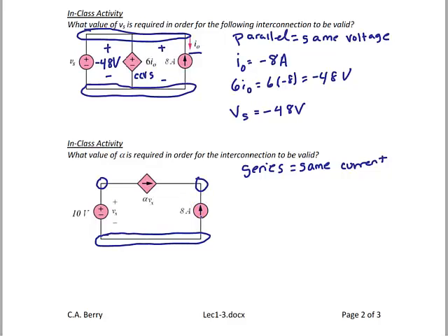So what that means is that if I have a current source of 8 amps that goes up, then I also have 8 amps that goes to the left, 8 amps that comes around counterclockwise and goes down into the 10 volts, and then the 8 amps returns at the bottom back to the source. So I have a voltage controlled current source here. My first task is to find the controlling variable Vx. Vx is the voltage across the voltage source. Since they have the same polarity, Vx is positive 10 volts.